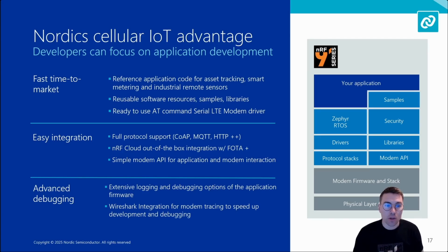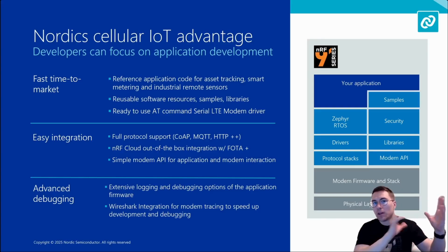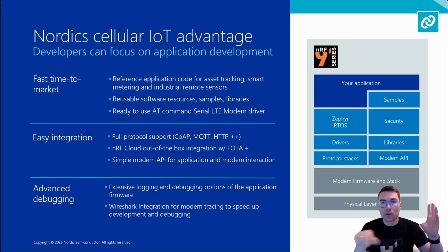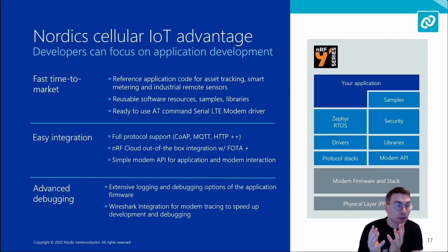We also have ready to use AT command LTE modem drivers, meaning you can select our device and use it as a modem only if you want to. So you can have a big host MCU if you want to have that, and just communicate with AT commands to our device, acting just as a modem and communicating with the cloud.